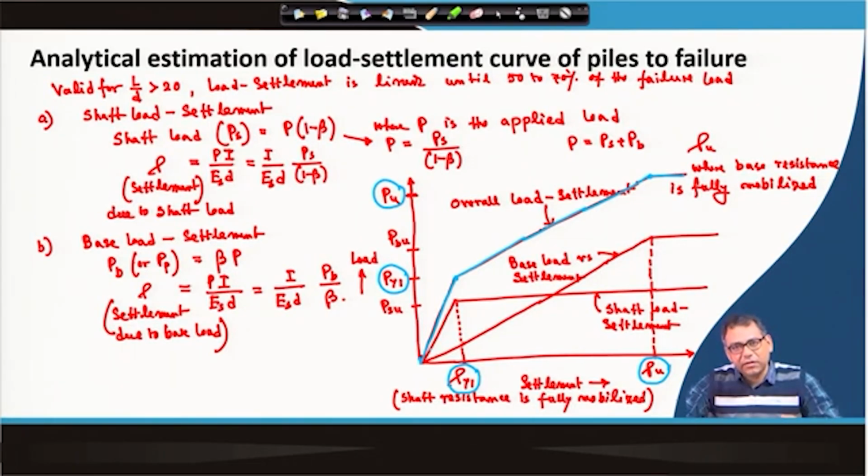That will affect the settlement of the soil, but the friction part component will not have any effect on the settlement of the pile material. The settlement of the pile material will be due to the load which is transferred to the tip of the pile or the base of the pile. That is one point.